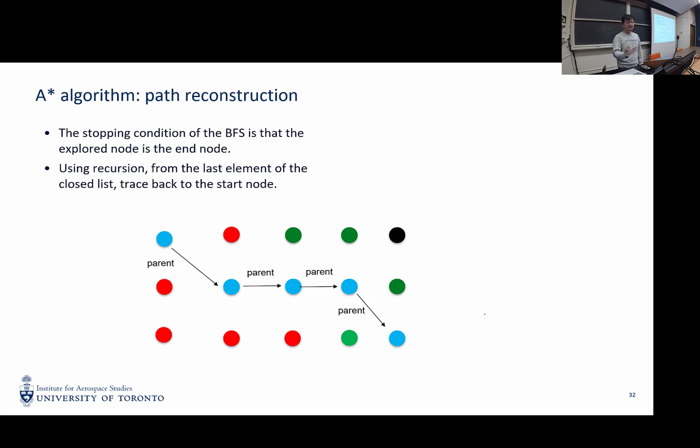And after that, if we do reach the goal location, we do the same thing as we have done in the RRT. We're going to reconstruct the path based on the parent index. So we can trace back from the goal location using the parent index stored in the data structure of each node. We reconstruct the path. So it's a backtrack to construct the path.